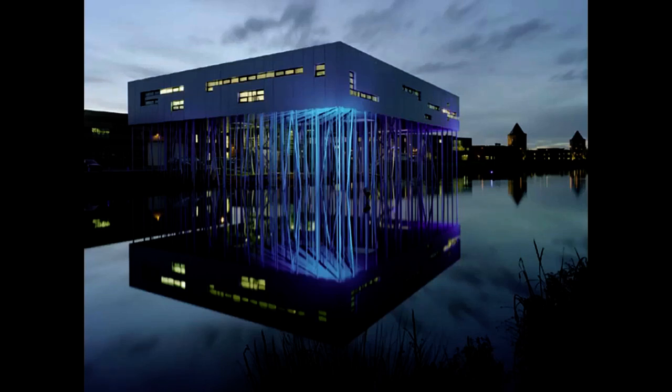These are aluminium columns. So now we've got a lot of them, and they're very small. It's almost the antithesis of the Parthenon, isn't it? Tiny sections, small sections, and again, look, they are not all perfectly vertical. That's a bit of fun, but it's not just a bit of fun. What's it doing? The moment you start to give any hint of triangulation, of course, you're stabilizing the structure against any kind of lateral load. So those ones that are raked, R-A-K-E-D, slightly not quite vertical, are actually working structurally.